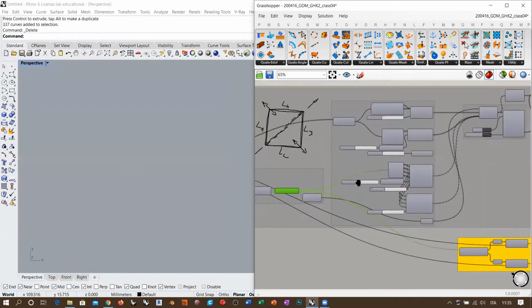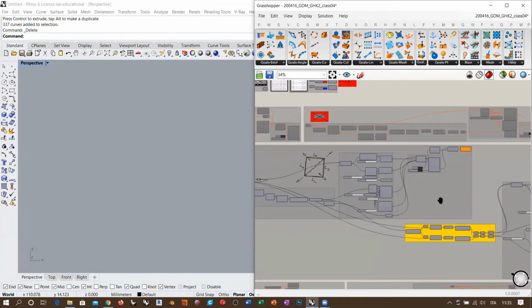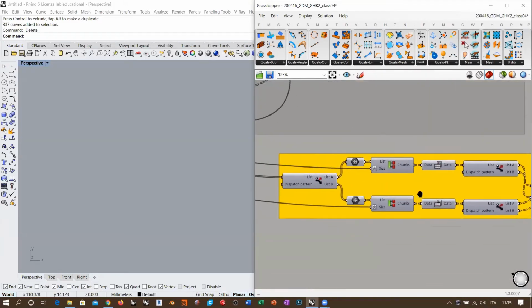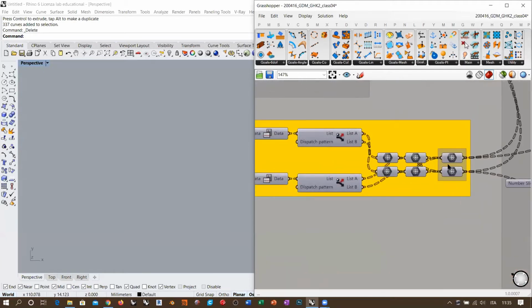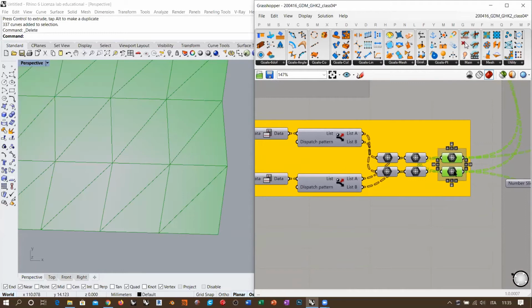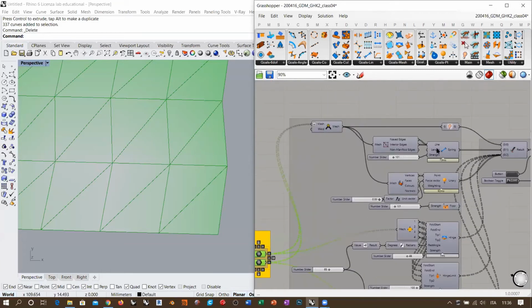And also here we had one single rest angle. They were all positive, and so this surface can only bend in one direction. Okay, while here what we did was considering basically the triangular mesh, which is this one. So we have also the diagonal edges taken into account in the elastic property definition.